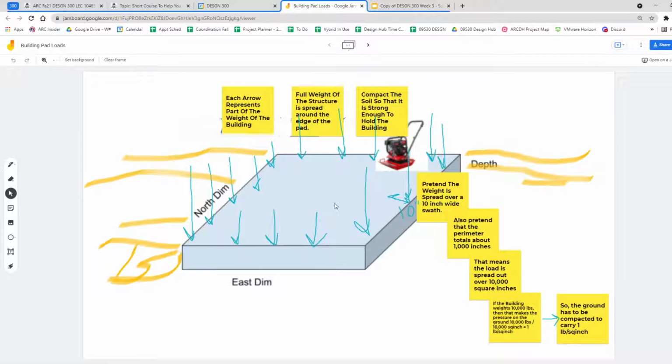And sometimes it's not very important. I'll maybe compact it 1/8 of an inch, or maybe even 1/8 of a foot, 1.2 inches or so. And that won't mean anything. But sometimes it really does mean something. And so, especially if you've got some tricky drainage and things. So that calculation is kind of important. And engineers may expect you to be able to figure out a percent change in compaction.